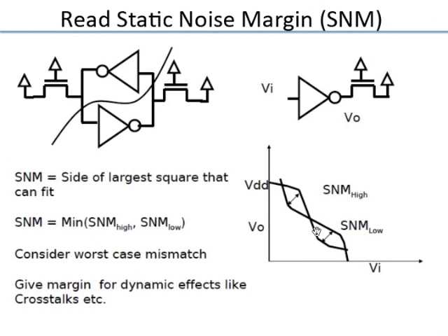Now this eye opening gives an indication of the robustness of the cell. So this is called a butterfly diagram because it looks like the patterns on the wings of a butterfly. If both the half cells were similar to each other, then you will have symmetry about this 45-degree line. Everything will look the same. But usually you will have some mismatches, and so the static noise margin SNM is the smallest eye opening. Whichever is the smallest, that is defined as the static noise margin.